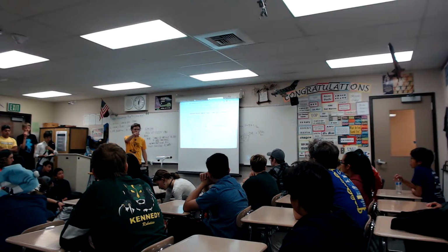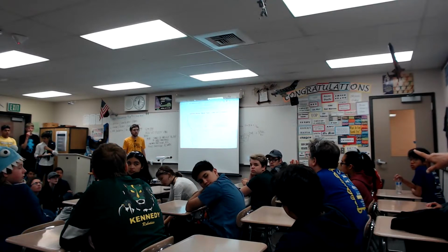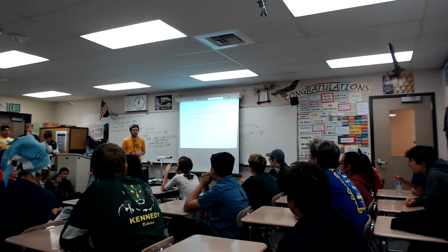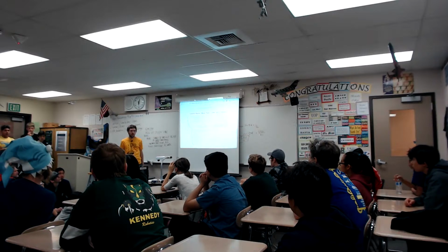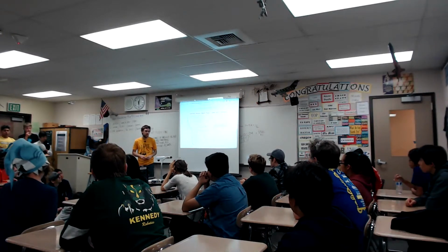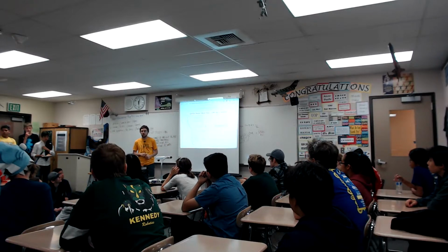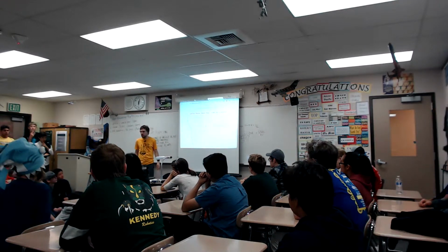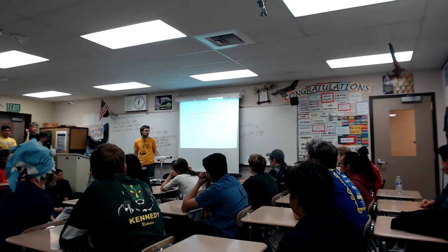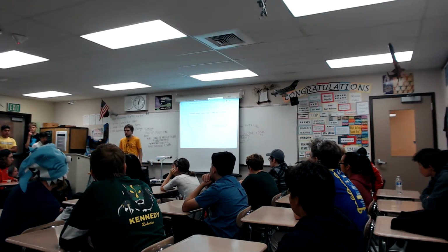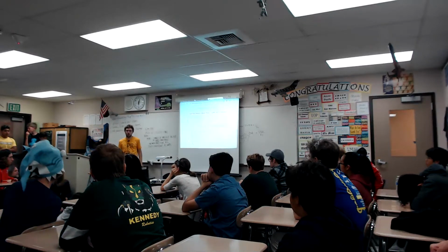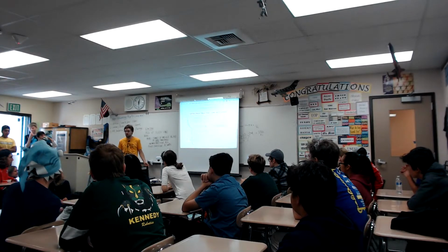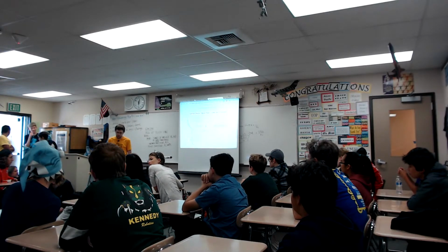Cool. Any questions here? Yes. So one of the things we're not considering is the impedance of the battery. Correct. You can model that with another resistor. We're going to get reasonably close to this equation, and at some point you need to go out experimentally, and we're ignoring gearbox inefficiencies and a bunch of other things. At some point you go run a test on your robot, and it will be pretty close to this, and then you can go fit some things, like model the extra resistance in your wire. What I tend to do is use the resistance as a lumped term for error. So if my robot's accelerating a little slower than I expect, I just up the resistance until it matches my model. You can run a little simulation and then have your robot drive the same thing and then see if they match. That gets you pretty close.